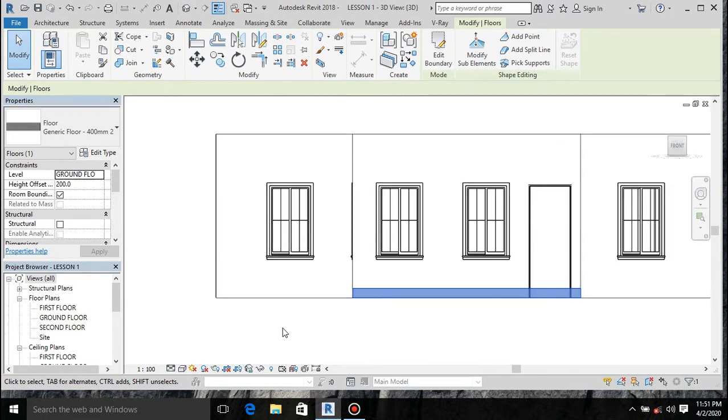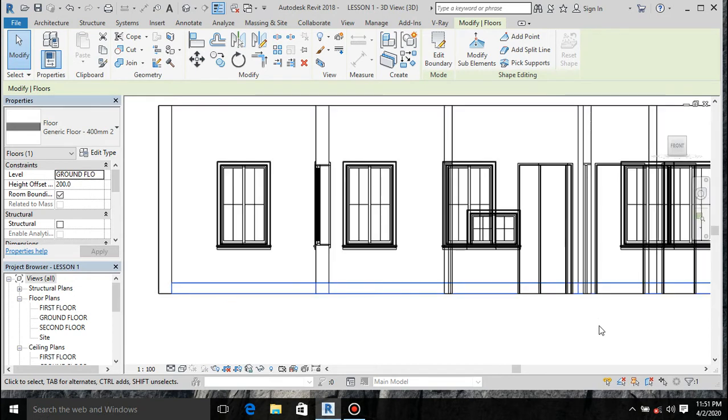Okay, good. Now you have to move the wall from here upwards. Wonderful. If you've noticed, I moved the wall, but I'm having problems. In wireframe, what's the problem? You see, these doors are at default settings. They should align with the base of the wall, so now it's not, because I moved my floor. I do not want a situation whereby I have the wall ending and my floor is at the ground, not a slab.